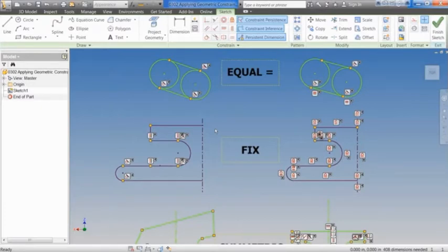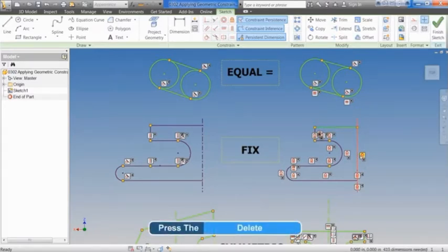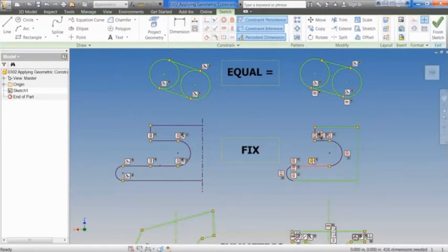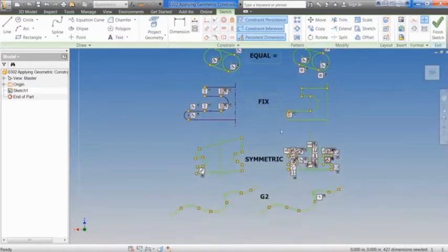It could get very frustrating if you came into a very complex sketch and a part of it was locked and you couldn't figure out what it was to be able to adjust it. I always tell people if they use the fixed constraint, use it sparingly and then turn it off when you're done. Easiest way to turn it off is just select it and hit delete on your keyboard. Ideally, you wouldn't be doing this many points whenever you're doing a locked or fixed constraint. But try not to leave it locked because it could come back and bite you later on.